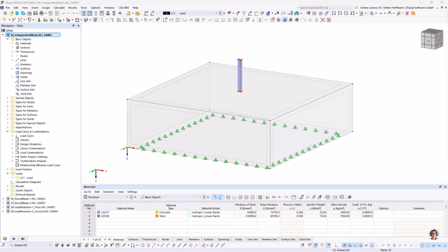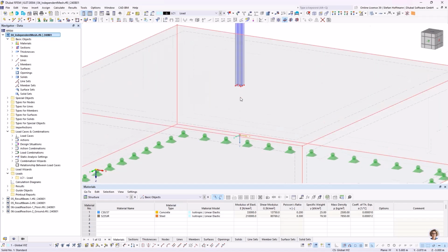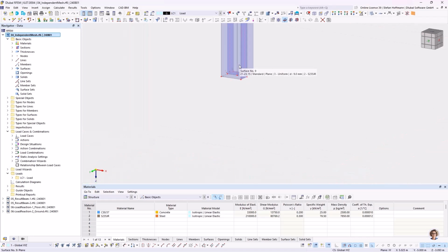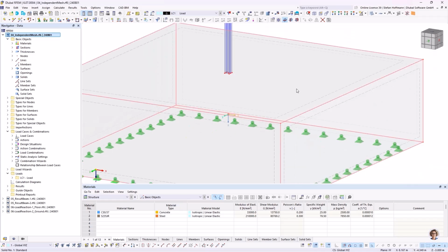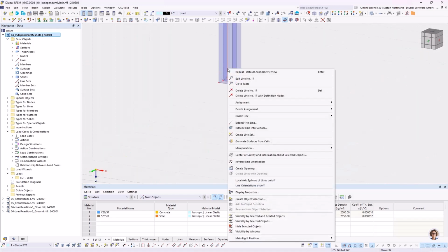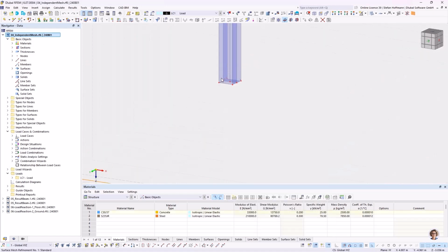So the next question is, can I generate the FE mesh of two or multiple objects independently? This question usually arises if you have a big solid, which can, for example, represent the ground, and then you have a girder or a beam connecting to it, represented by surfaces, with a fine mesh of these very thin surfaces next to the solid, because we propose that the solid mesh should be at least 4 up to 8 elements per thickness. It may of course be even finer.